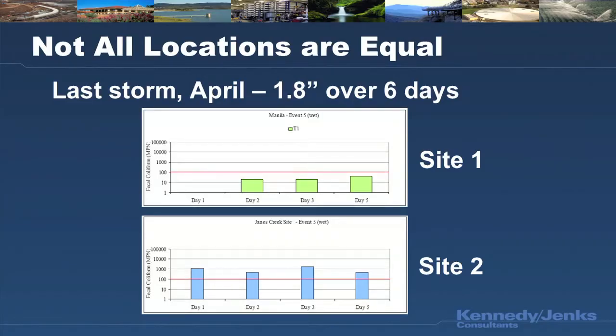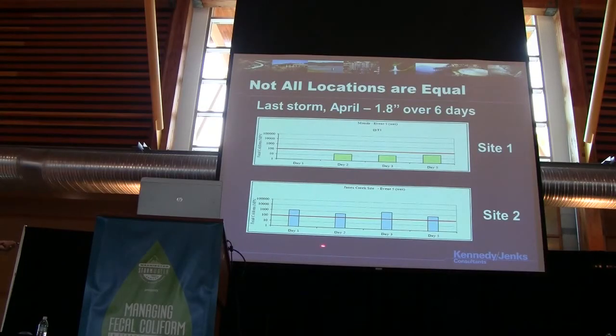The next study compares two different sites at the last storm event. Previously it showed it's below the 100 ml value, and the adjacent site showed that even though this was the last storm, it still had high coliform levels, as much as 1,000 coliform per 100 ml. These are all from fairly large catchment basin structures, about 48-inch diameter drainage pipes.